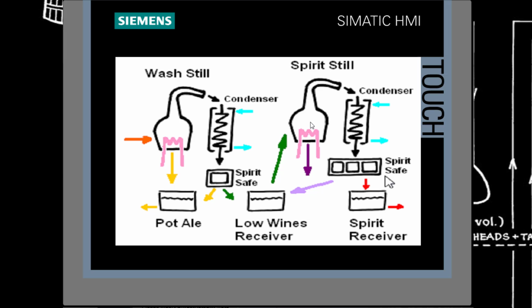Now the density measurement and the temperature measurement inside the Coriolis meter is pretty linear in its uncertainty, so that's not where the error is. The error is actually in the OIML tables, and if you were to look at the curves, they're not linear, and that's where we get the problem. It's the actual characteristics of the process, or the measurement of ABV, and the formula that it's based on is not linear, and that's why we need to have the split ranges.